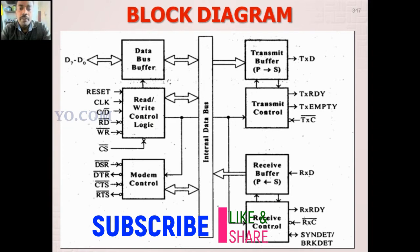First we will see them one by one. First one, we are going to see the data bus buffer. The data bus buffer is connected with the 8086 microprocessor data lines. So this is D0 to D7, the data lines. It's an 8-bit data bus buffer.